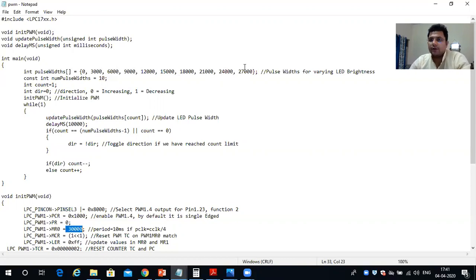Now that is our aim, so how can we do it? Obviously you have to configure the registers. How will we configure the registers? We will require the timer function. We want to introduce a certain delay so that we can realize that something is going on, and we can understand the transition of the increasing voltage level through our pulse width modulation.